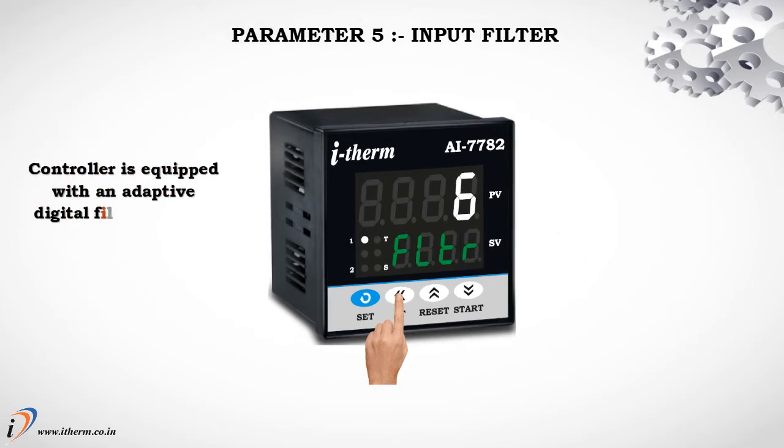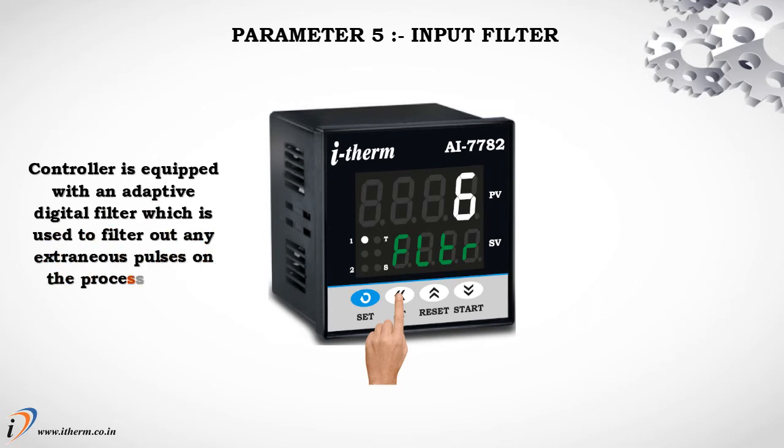Parameter 5, Input filter. The controller is equipped with an adaptive digital filter which is used to filter out any extraneous pulses on the process value. Default input filter value is 6.